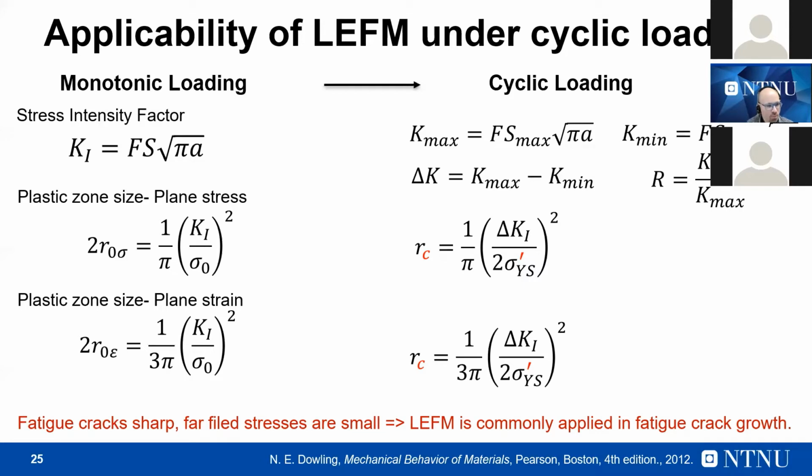This is also very important if you have, for example, a torsional case, because under torsion, usually the energy at the crack tip is mainly deviatoric energy. This means that the plastic deformation is much larger, and so you can find a bit larger plastic volume also at very high cycle fatigue or at high cycle fatigue. So torsion sometimes can be a problem because the plastic volume of the material close to the crack is very large also at low load level, so at high cycle fatigue.